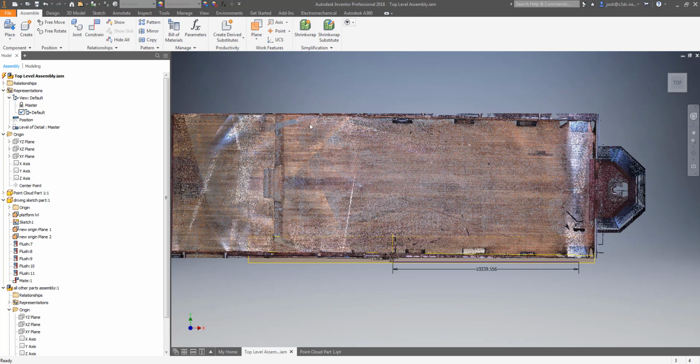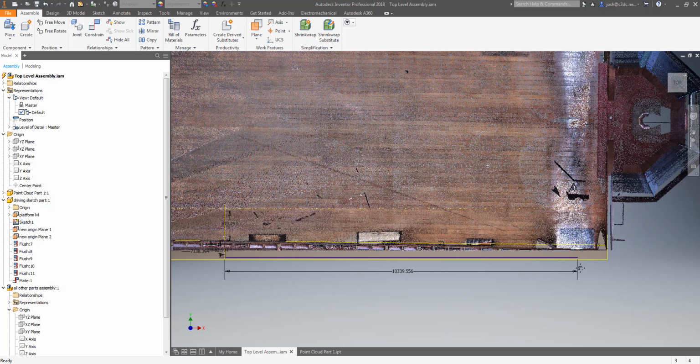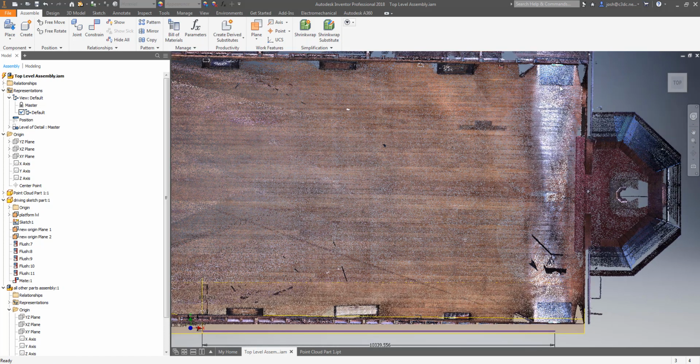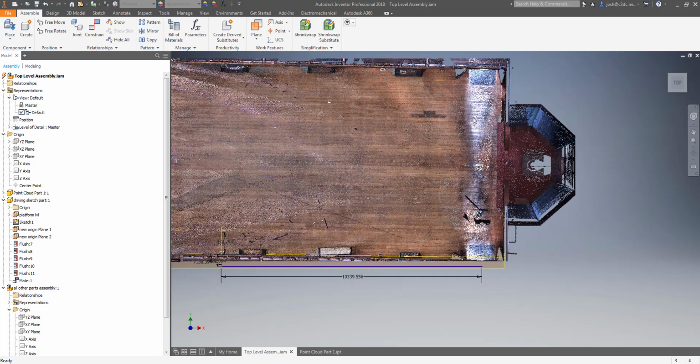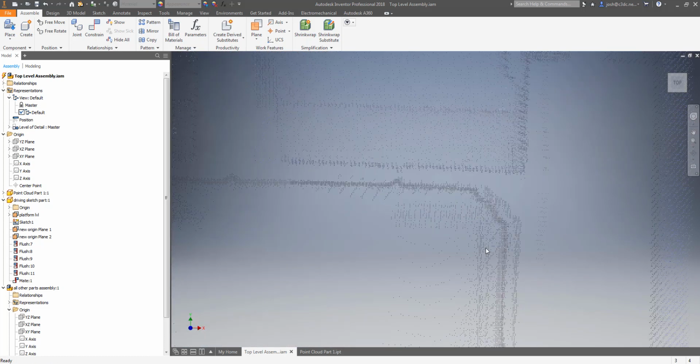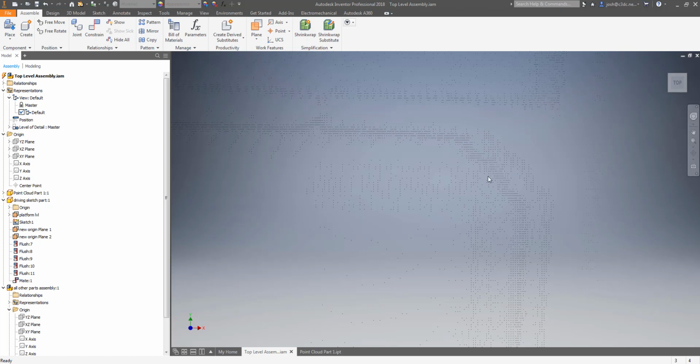If we look at the point cloud in plan view, you can sort of make out the walls and doors here, but the detail is a little too hard to make out. You will also notice that if you zoom too close to the point cloud to get a better view of the detail, it turns into this unrecognisable mess of points where you can't make out any features. The reason that this happens isn't the fault of the program or the scan data though. The reason that this happens is the points are just that, an infinitely small point in 3D space. Any program that displays point cloud data adjusts the size that it displays the points at depending on the zoom level. Anyone familiar with working with PD mode and PD size functions in AutoCAD will be familiar with this concept.